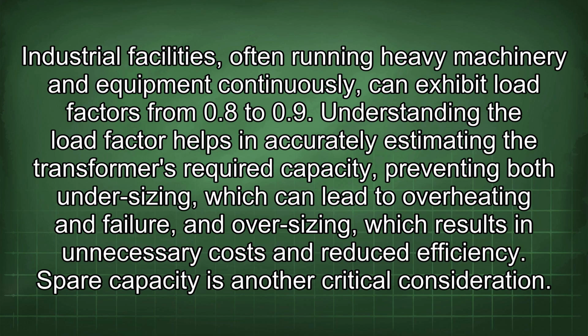Understanding the load factor helps in accurately estimating the transformer's required capacity, preventing both undersizing, which can lead to overheating and failure, and oversizing, which results in unnecessary costs and reduced efficiency.